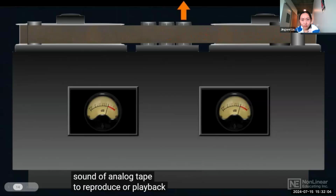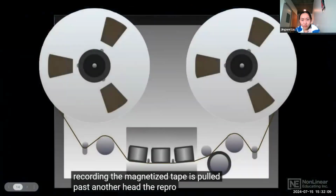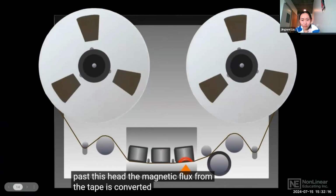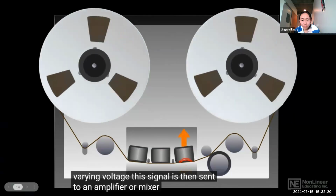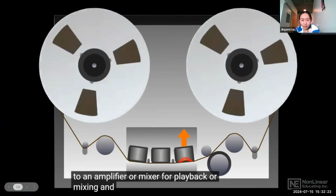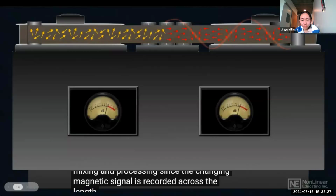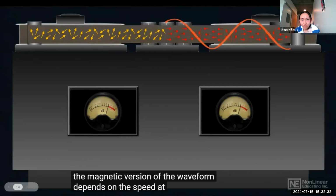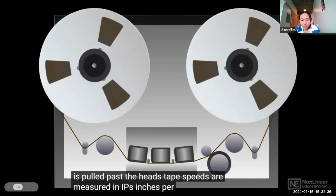To reproduce or play back a magnetic recording, the magnetized tape is pulled past another head, the repro or playback head. As the magnetized particles on tape pass this head, the magnetic flux from the tape is converted back into a varying voltage. This signal is then sent to an amplifier or mixer for playback or mixing and processing. Since the changing magnetic signal is recorded across the length of the tape, the actual length of the magnetic version of the waveform depends on the speed at which the tape is pulled past the heads. Tape speeds are measured in IPS, inches per second.